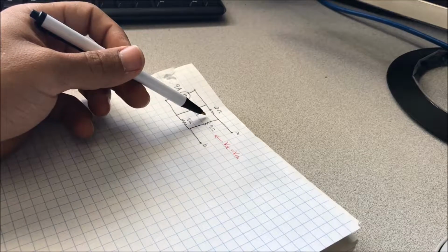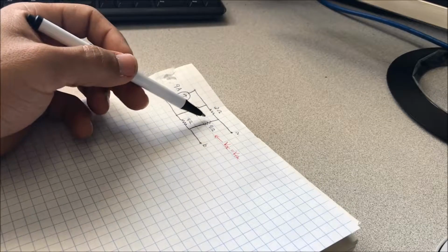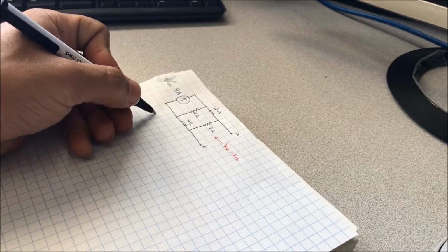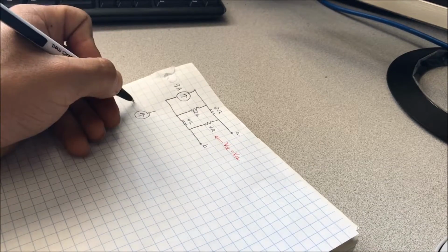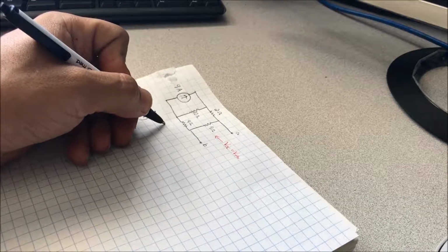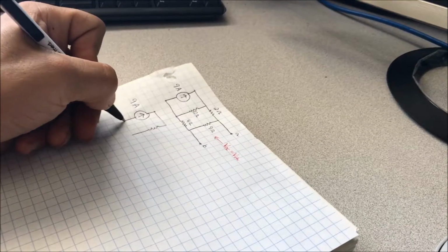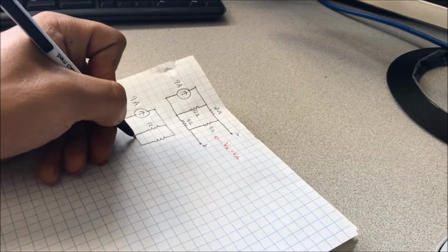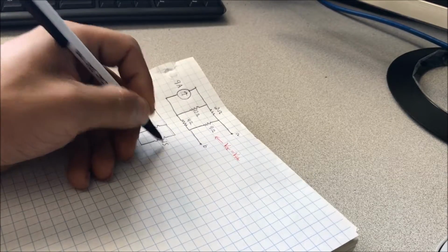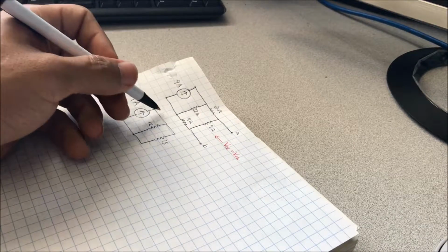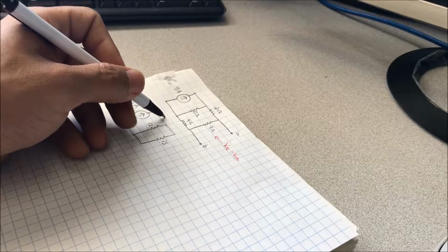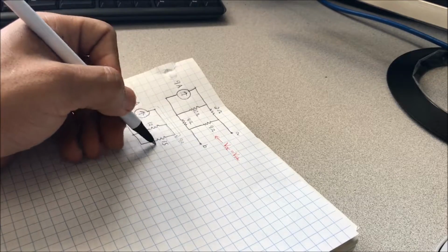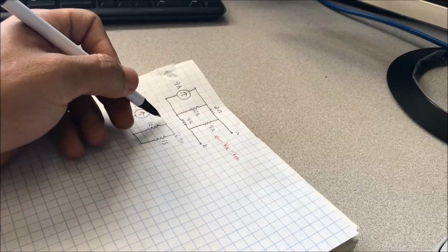Now if you look at this right here, the 2 ohm, the 9, and the 4 are all in series, so what we can do is just add those up, and the new circuit will look something like this. The 12 is there. Adding those three up, we get 15. Now if you look here, the current goes around, so that's the 9 amp going through both branches, the 12 ohm and the 15, so it gets split.